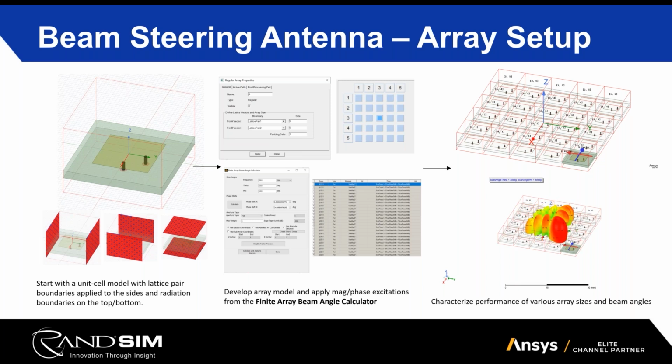So if you think about a 5G millimeter wave base station, that's often going to be comprised of some sort of an array antenna. The benefit of an array is that, if we recall from that initial image, the gain was maybe 8 dB at its peak coming off the top, and it's relatively omnidirectional around the horizon. It's mostly just kind of a big blob. It's not very narrow and focused. So it's radiating its energy more or less equally in a general direction away from the patch.